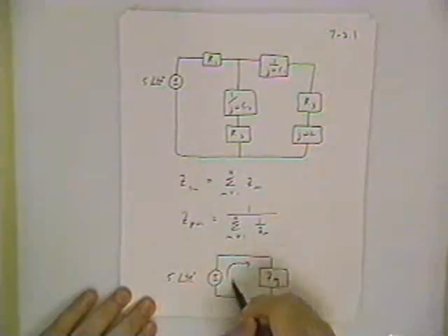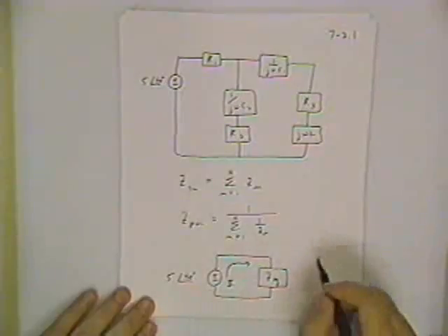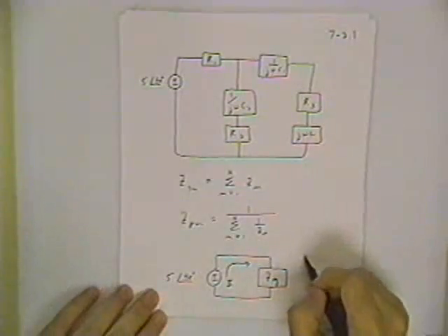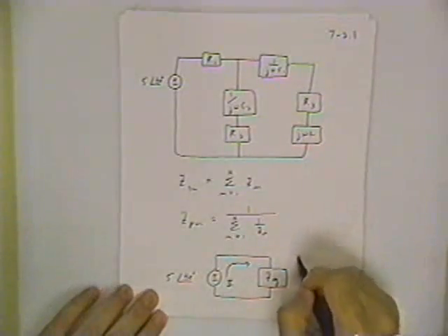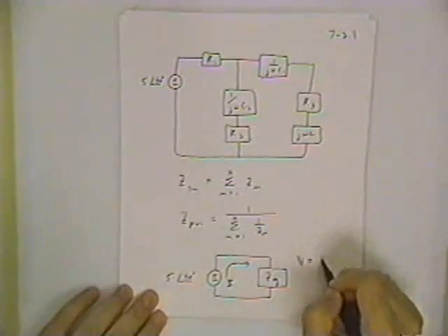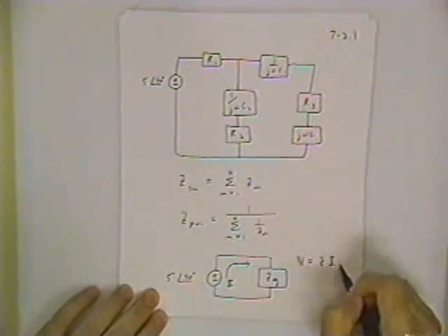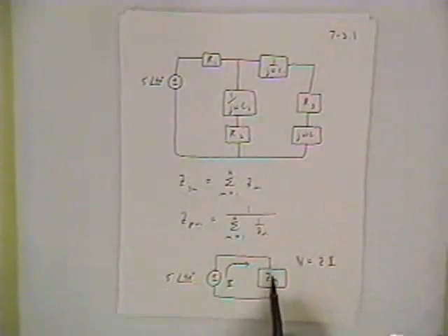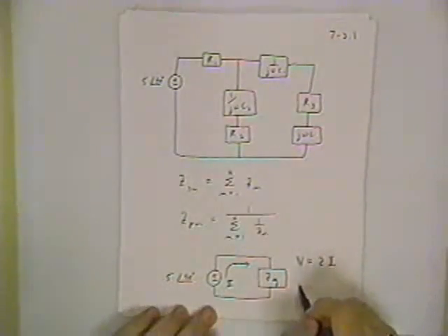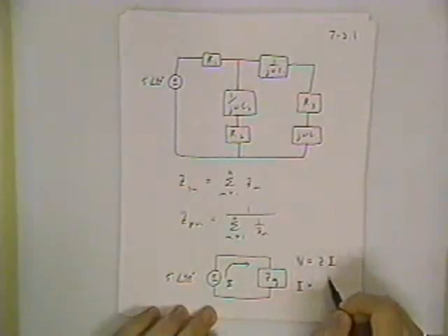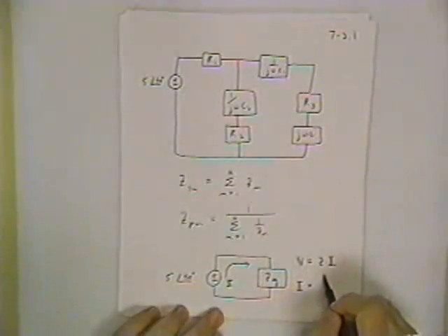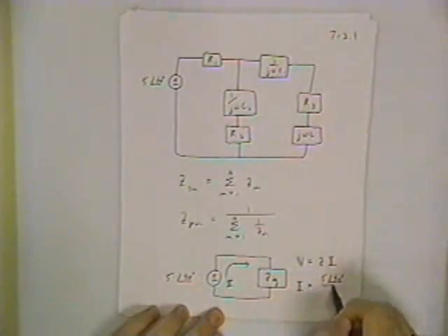And from that, I can easily calculate the current, because just as we have Ohm's law, V is equal to Ri, we've got the AC equivalent of Ohm's law, V is equal to Z times I. And I would calculate the I in this circuit with V phasor divided by ZEQ.